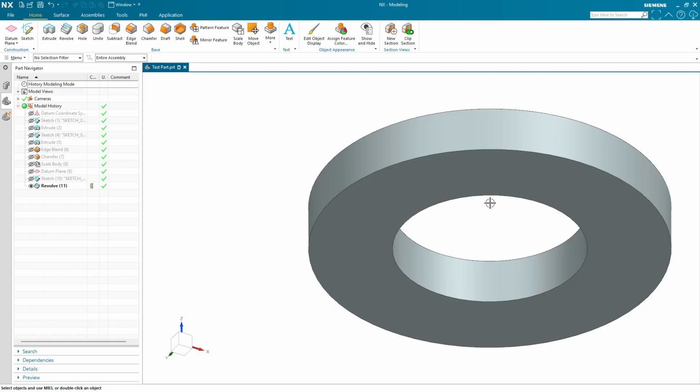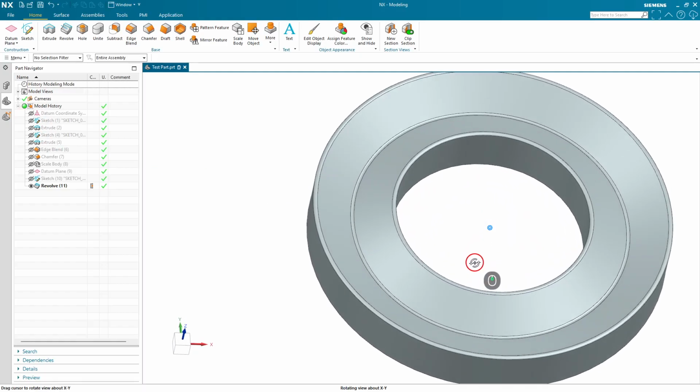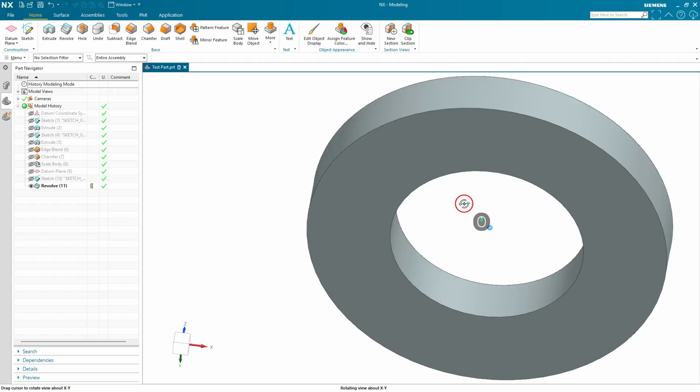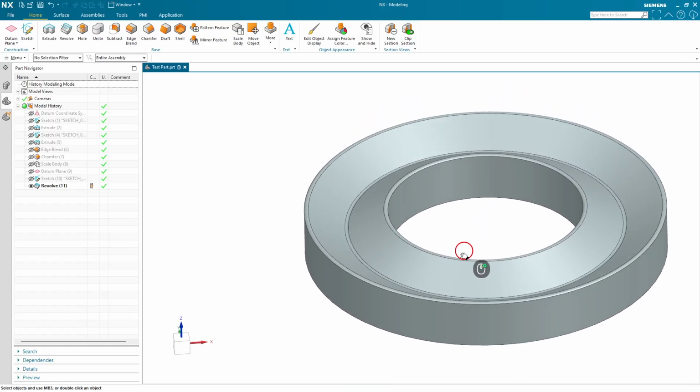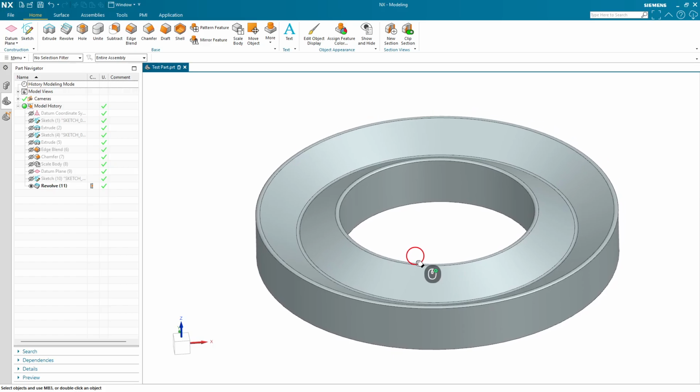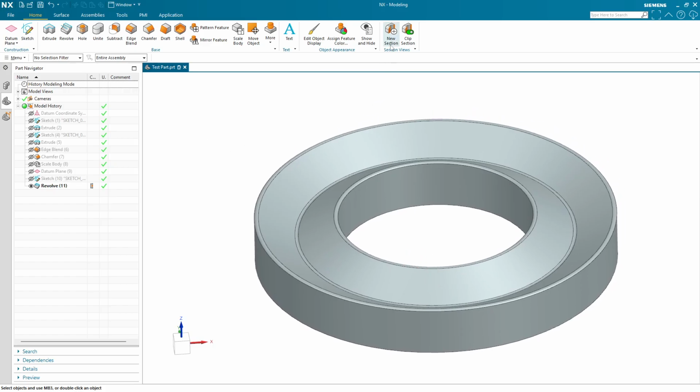And at this point, we want to check, do we have the internal channels? Like, we can't see if they're there. We have no idea if that heptagonal and circular channel made it in here. So what you can do, again on my roll, or you can search in the command toolbar up here, is you can press New Section.